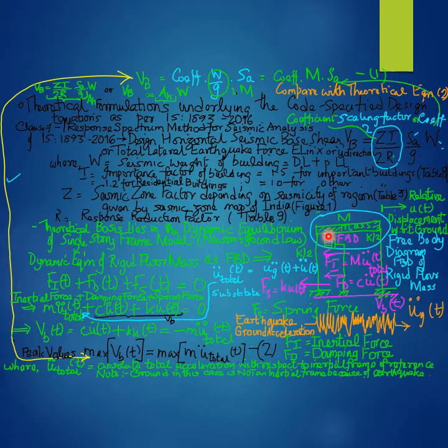The traditional symbol of the dash pot shown in the figure represents the natural or viscous damping of the single story frame model, which induces a time variant damping force that is denoted as F subscript D, also a function of time, and acting in the direction opposite to the earthquake ground motion, as well as the relative displacement or the only single degree of freedom of the single story frame model, that is U.